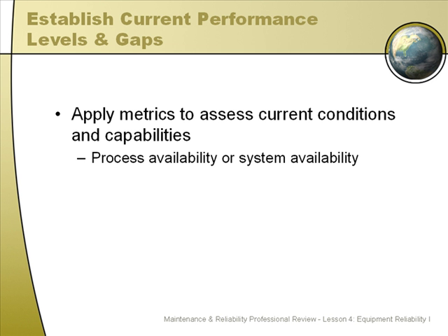Now here's another point that we talked about already: process availability or system availability. You can calculate availability across a whole process rather than just one piece of equipment. And this is not that complicated. It's just basically the compounding of the same calculation across multiple pieces of equipment, and it's easily measured. Typically, you can get this information from your distributed control system or from your CMMS. But if you don't have those tools, it's time to start thinking about an upgrade.